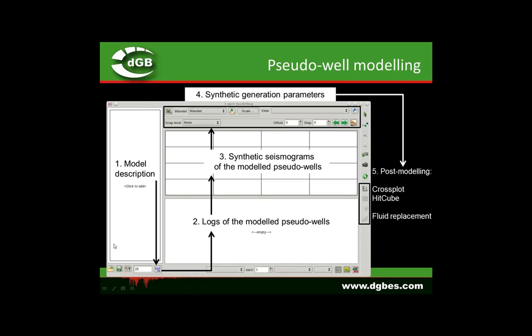First of all, you'll need to build your model. So in stochastic mode, the model is built here on the left-hand side, and then when pressing go, you'll generate your pseudo-wells. That is for the stochastic mode. In the profile mode, the modeling is actually done in the same window as we use for displaying the modeled interpolated pseudo-wells that are always displayed at the base of the SynthRock layer modeling window.